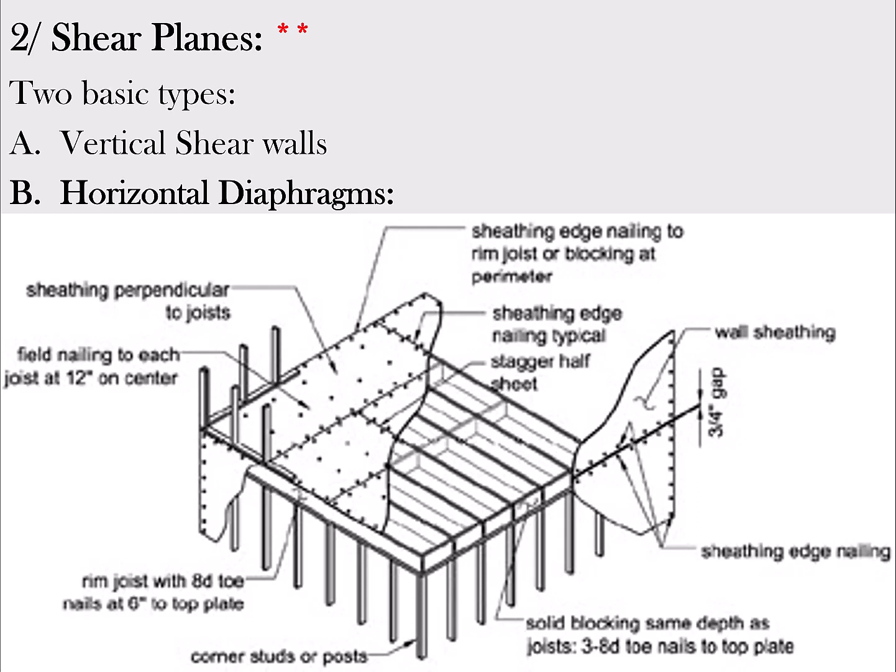So this is a floor system, but when you put that plywood sheathing down with a proper nail pattern on it, you make that floor rigid and it becomes a critical part. On a typical concrete basement wall, those walls are not strong enough to support the dirt, the backfill, until you have that floor system installed on top of that wall, because that's what braces the top of that concrete wall. So it's an important structural element for a concrete basement. You're typically not allowed to backfill that concrete basement wall until you've got that floor system fully installed and inspected.